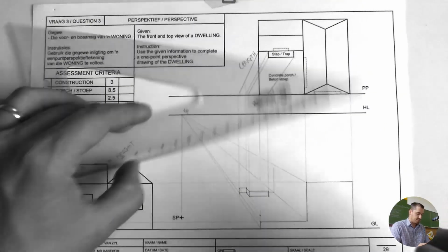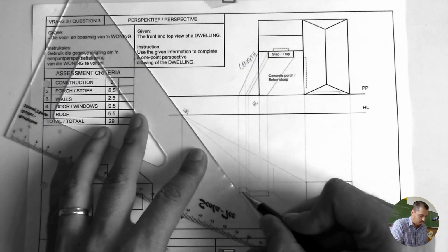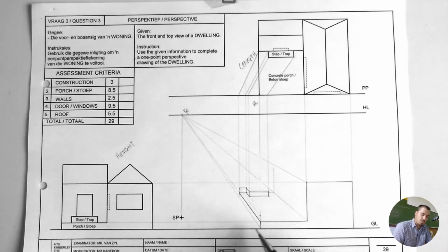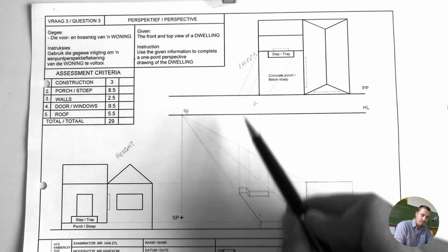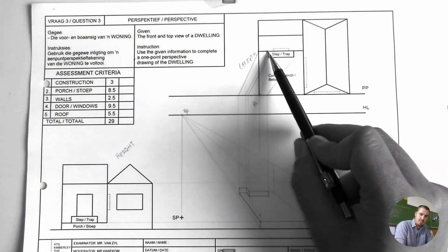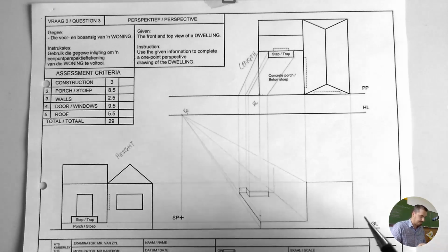Right, I'm just darkening the lines so we can see exactly what we are working with and what we have done so far. Alright, so this is going to give you the indication. What I've done, the step goes onto the height line, so that's the height for the step, goes to the back where it connects here on the back line, right, so it's in line here. Then that point goes over to the right until it connects onto that inside point of the step, and then I can just start projecting it so I have the height.